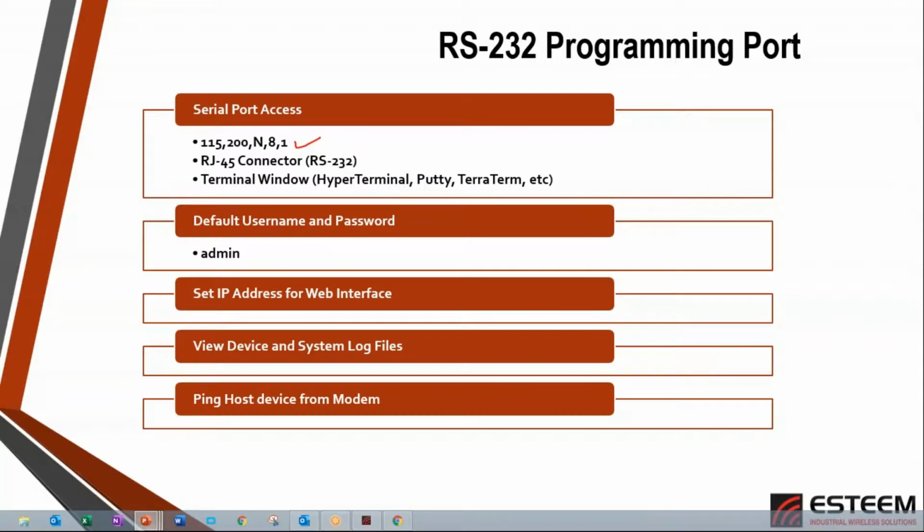It uses the same username and password that is set in the web interface, so if it is changed, you'll need to enter it there. It allows you to do a shorter subset of the communication available in the radio. It allows you to do the critical things, let's say, where you need to change the IP address, or look at the log file, or we can actually go in and ping directly from the radio itself to verify that the communication is there.